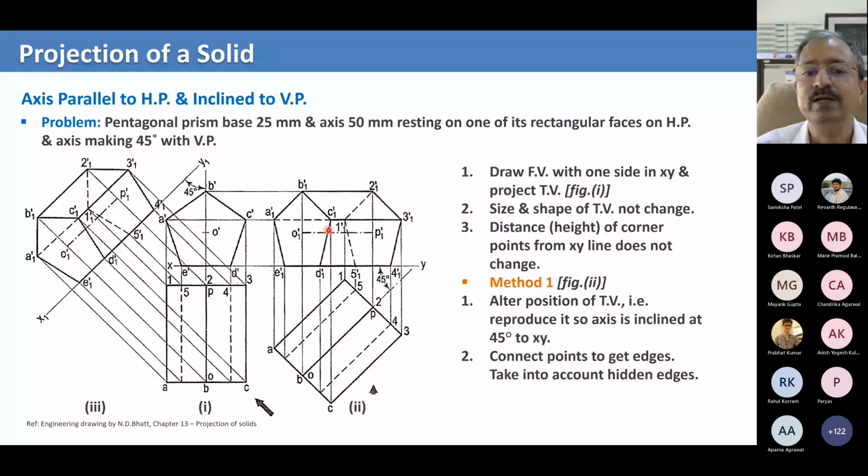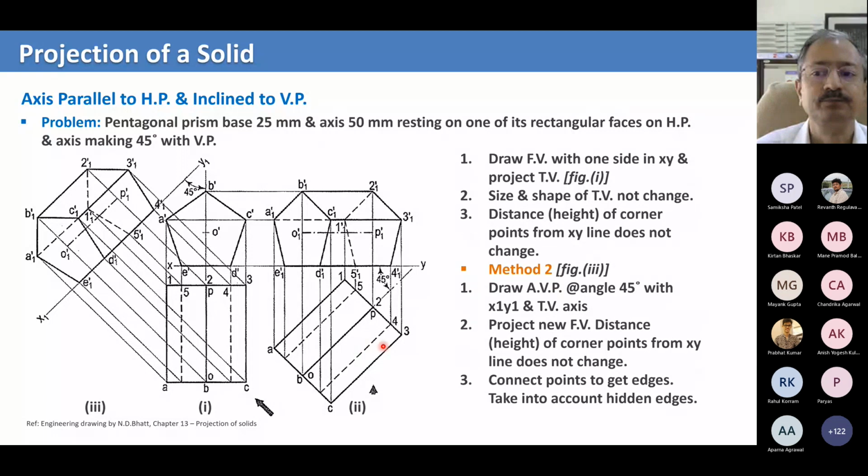And similarly, on the other side, this face, and this is represented by the distance between the two dashed lines, because this bottom face is not visible from the top. It is a hidden line. So what you're seeing here is the hidden projection of your base. Okay, so once you figure out that, construction is straightforward for you because you already know the construction of even the planes, right? But again, this is a simple case because the base is parallel to the horizontal plane.